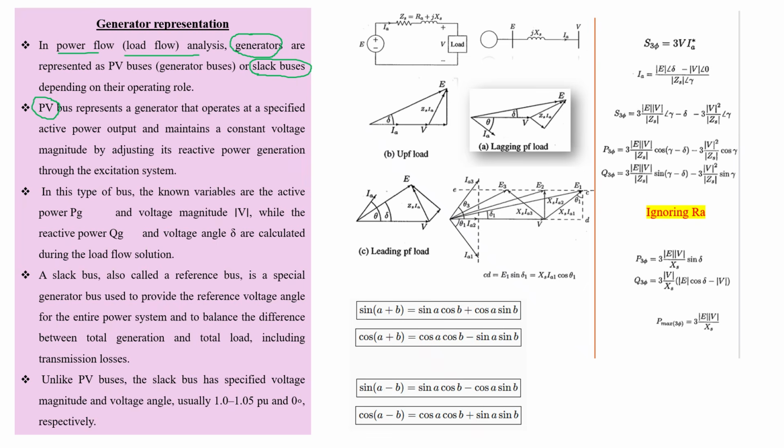In addition to that, in a power system we'll have a PQ bus, where active and reactive load are already determined, so we calculate a voltage and a voltage angle. The calculation of this voltage and angle is done by using an iterative method. Maybe we can apply Gauss-Seidel iteration and other iterative methods to determine those parameters.